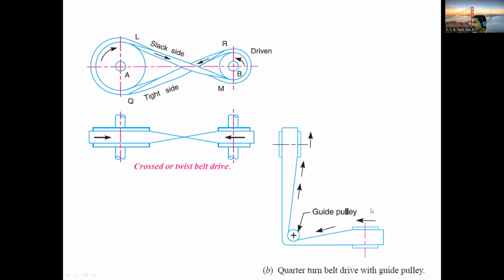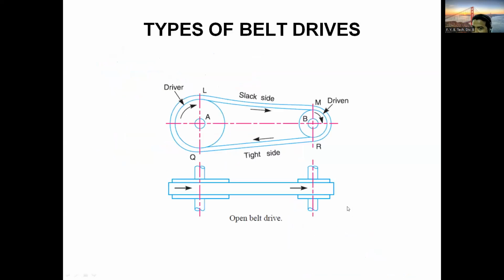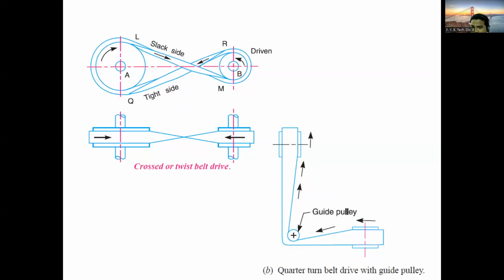If you observe properly, the belt covers the maximum portion of the pulley. You see the arrangement of open belt wrap. Comparatively it is less. Angle of lap is what? In case of open belt wrap it is less, but in case of cross belt wrap angle of lap is more. Hence amount of power transmission will be more. Getting?